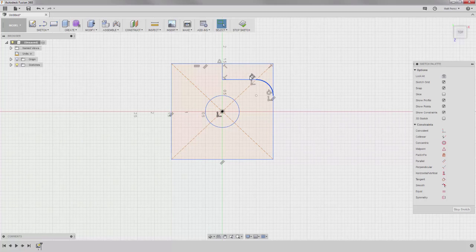The circle with the line signifies a tangent constraint. The icon shaped like an L signifies coincident constraint, and the two lines here signify a parallel constraint. If you hover over a constraint icon, it will highlight the entities connected by the constraint and any related icons. This icon shows a horizontal constraint was applied to one edge, and the others are either perpendicular or parallel.